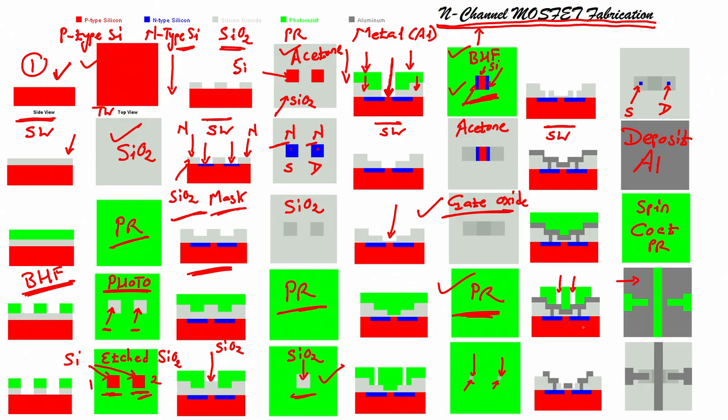Then you etch the metal. You know how to etch the metal now, right. So, when you etch the metal, what you see here? There is a source connection for metal, there is a drain, metal is connected, and here is your gate, right. So, what you have done? You have now understood the process flow for n channel MOSFET.